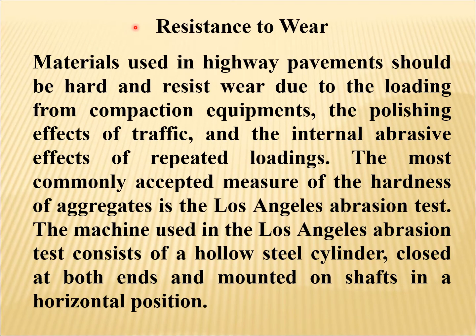Then look at the resistance to wear. Materials used in highway pavements should be hard and resist wear due to the loading from compaction equipment, the polishing effect of traffic, and the internal abrasive effect of repeated loadings. The most commonly accepted measure of the hardness of aggregates is the Los Angeles abrasion test.